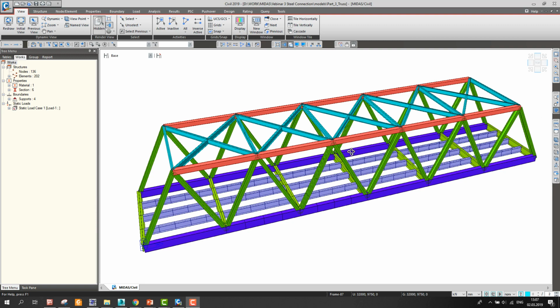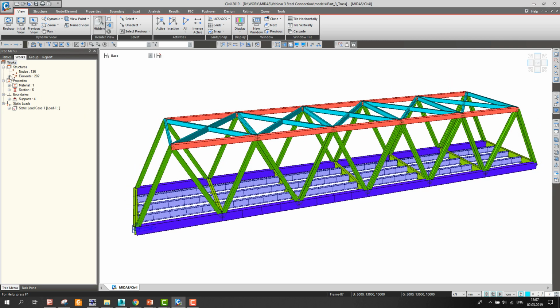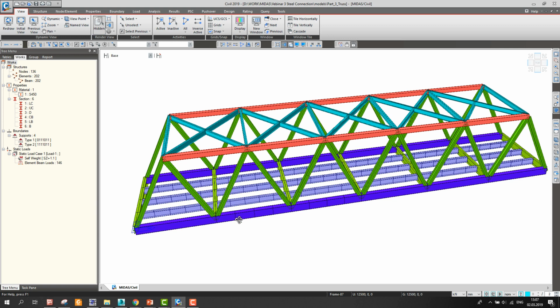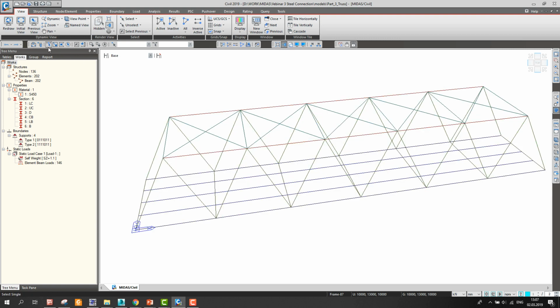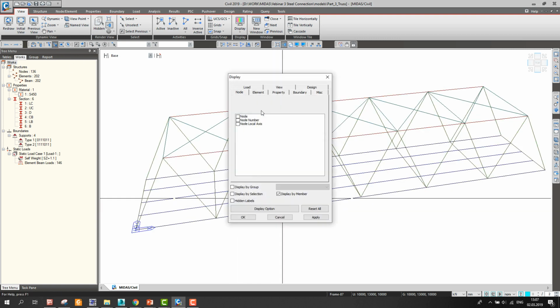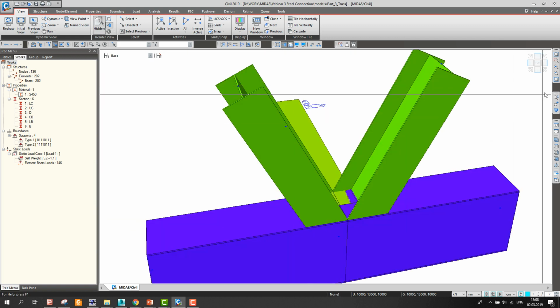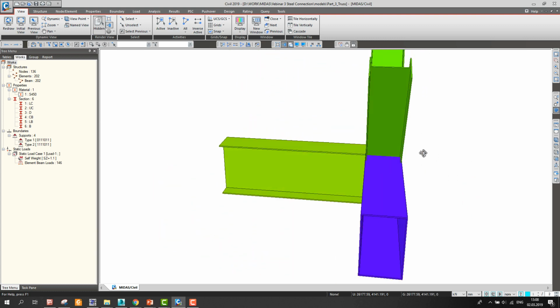This is a global model in Midas Civil. This model is created using beam elements. It has some materials, some sections, some boundaries and loads. In the place where I want to consider my connection, I approximated lower chord and diagonals with many elements to get my nodes for displacement extraction. And by this way, I established dimensions of my detailed shell model.